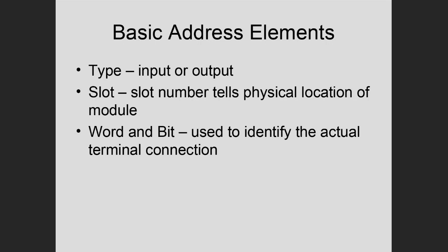So there's no standard address. The address schema depends on who makes the PLC. All manufacturers have different addressing schemas. And for some, like Allen Bradley, depending on which model PLC you buy in that family, there may be several different address schemas. This one, which I'm going to show you in just a second, is based on a particular Allen Bradley PLC family. But basically, the address will give you this information.